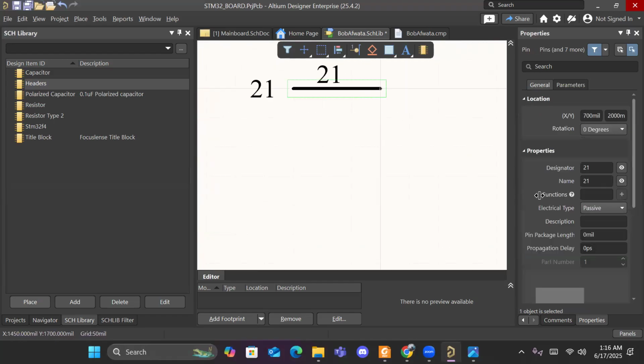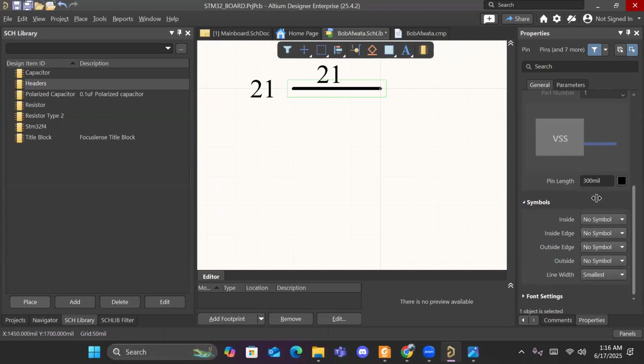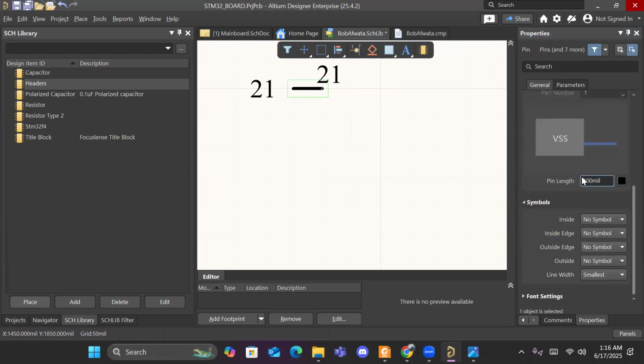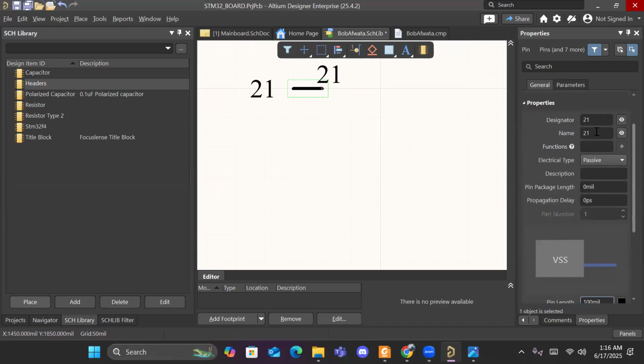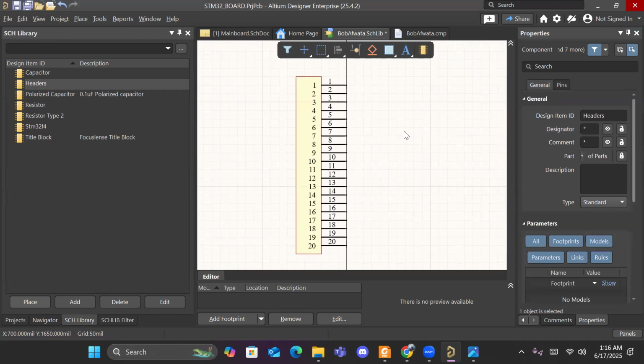So click on it and then come down here to designator, you want to change the length to something. It's not a line, it's the pin. It's a pin, not a line. Here, place pin. Have you seen it now? I was using lines. Okay, let's make that correction.